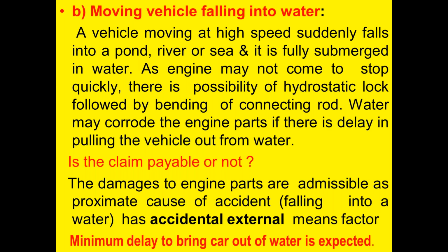Moving vehicle falling into water. A vehicle moving at high speed suddenly falls into a pond, river or sea and is fully submerged in water. As the engine may not come to a stop quickly, there is a possibility of hydrostatic lock followed by bending of the connecting rod.